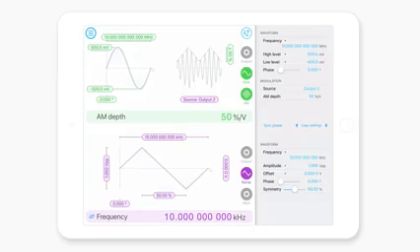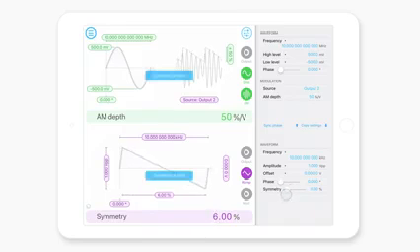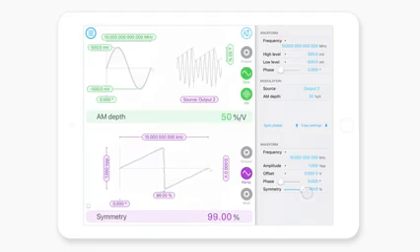So you'll notice here that channel 2 is producing a sawtooth wave with a symmetry of 50%, and the amplitude of the sine wave on channel 1 is now also being amplitude modulated by that signal. What's really cool is that as I adjust the symmetry of the waveform on channel 2, it updates the modulated waveform on channel 1. And this is a really neat feature if you need to modulate the waveform with some exotic shape.